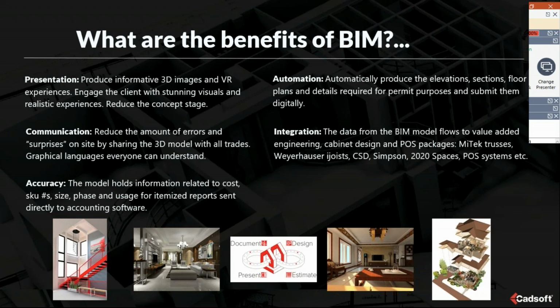The biggest key benefit of BIM is the integration. If I draw one model, I should be able to pull information to flow to all of the other pieces of software that I may be using or different workflows that I have. So if I'm doing cabinet design and someone else is doing the cabinets for me, and that cabinet shop is using one piece of software, I should be able to absorb their information in or export it back out to them. We should be able to share information. If I'm going to be building trusses for my model, I should be able to send my model out for truss design, and they should be able to use that model.